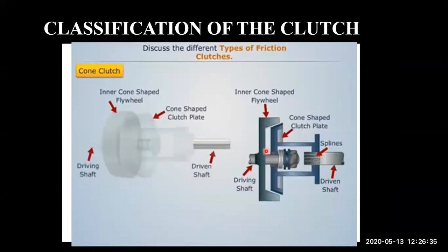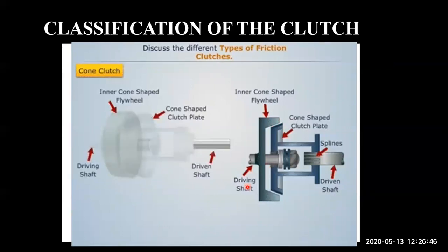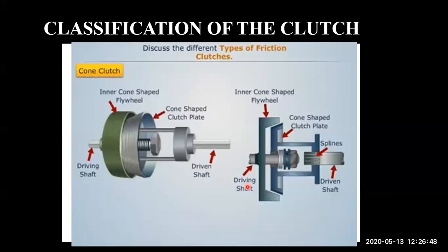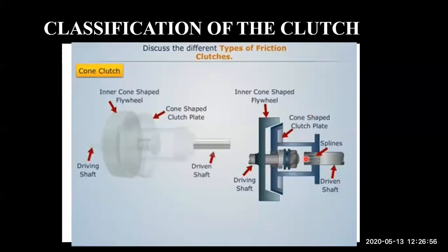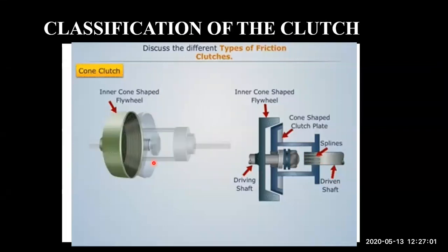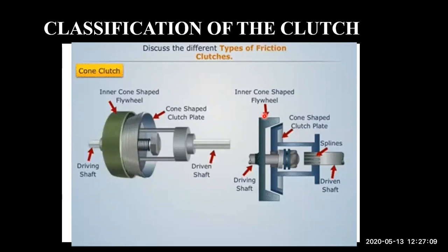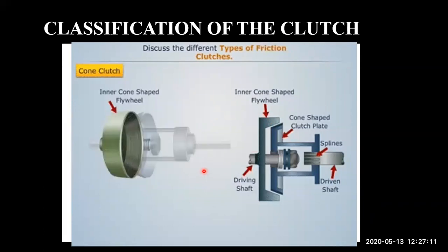So advantages, you have a bigger surface area which can engage better, and also exit from it better, in a uniform fashion. You can engage and disengage in a much more uniform manner. Again, here you are using the spline shaft to engage and disengage. And you can see here the friction lining, which is mating with this flywheel, which is also in the cone shape.